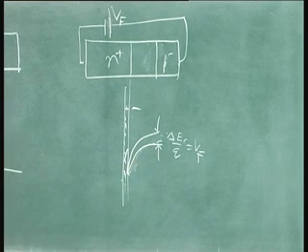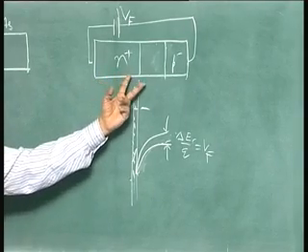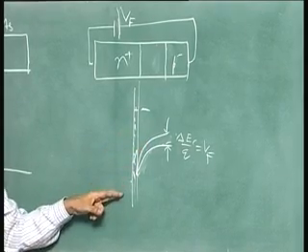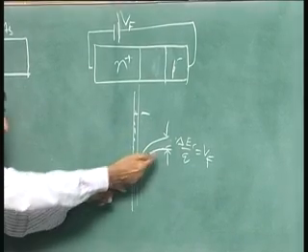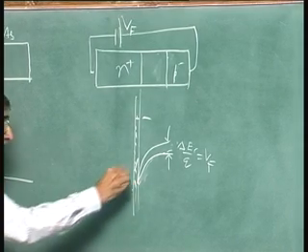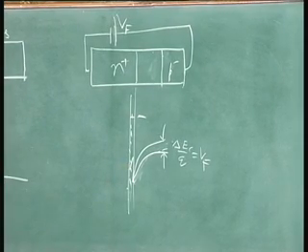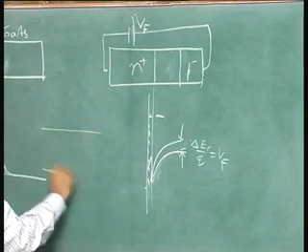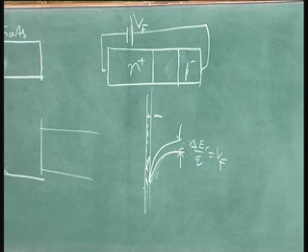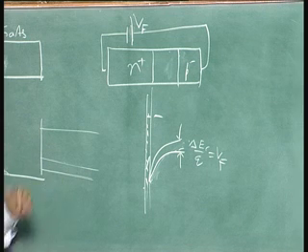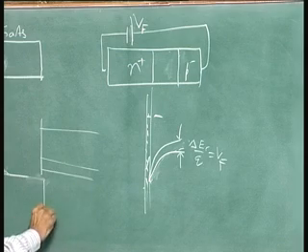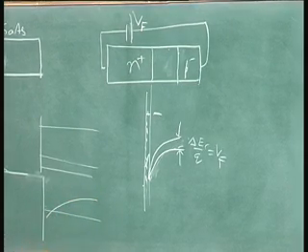What we are trying to point out is, by applying a forward bias like this, I am reducing this potential change. Therefore, the band bending is reduced, and therefore the charge here is reduced. For example, if you take a p type semiconductor, the Fermi level is there, under thermal equilibrium conditions, no depletion layer, but when the depletion layer comes up, what happens?